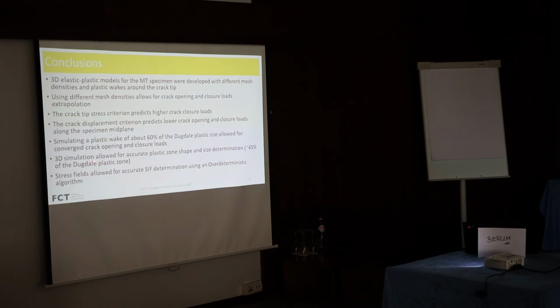The 3D simulation allowed for accurate plastic zone shape and size determination, and finally the stress field allowed for accurate stress intensity factor determination using the over-deterministic algorithm.